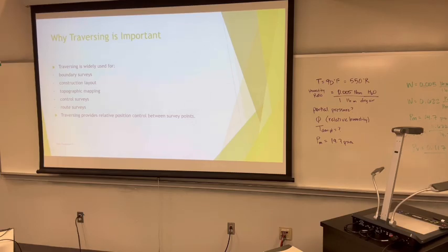We could really go into a deep rabbit hole as far as what types of control, where you would set it in regards to a project. Again, it all varies on what you are doing. Boundary surveys, you're probably not going to be there very long. You're going to run around the property, locate the monumentation and evidence of occupation around the property lines, and try to establish where they are. Probably not going to be there too terribly long.